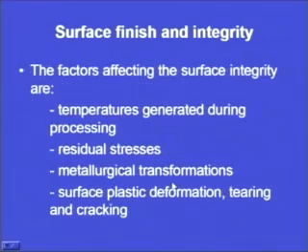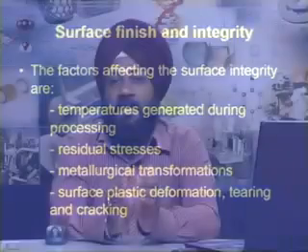Now, surface integrity incorporates an important point, that is, it will affect the fatigue life and corrosion resistance. We can take a lead from here: surface plastic deformation, tearing and cracking. If cracking is taking place on a surface, or the surface that we are generating has certain cracks on it, then however small these cracks are, when we use the component for cyclic or fatigue loading, these small micro cracks have the tendency to enlarge. Some micro cracks may join together to form a bigger crack, and this crack may later on lead to the catastrophic failure of the product that has been machined with a surface that had micro cracks.